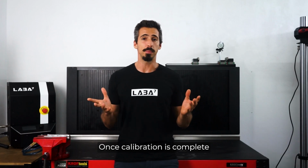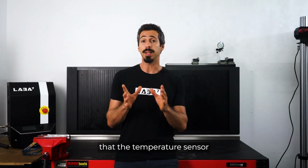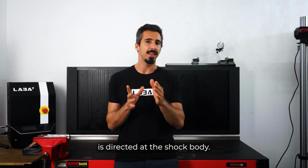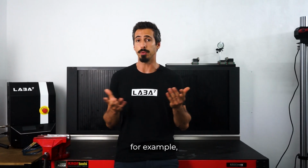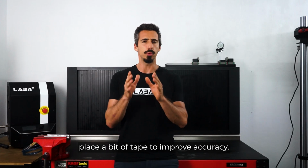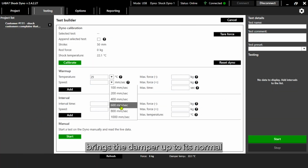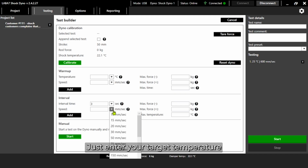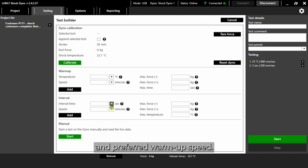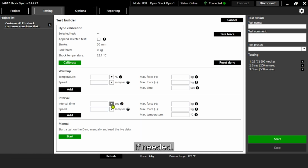Once calibration is complete on your Scotch-Yoke dyno, it's time to run your test. Ensure that the temperature sensor is directed at the shock body. If the surface is reflective, like chrome-plated for example, place a bit of tape to improve accuracy. Start with a warm-up. This test brings the damper up to its normal operating temperature. Just enter your target temperature and preferred warm-up speed. You can also set optional force or time limits if needed.